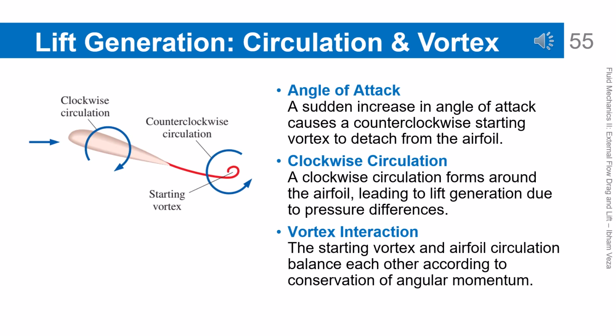Lift generation through circulation and starting vortex. When the angle of attack is suddenly increased, a starting vortex is formed and shed from the airfoil. At the same time, a circulation develops around the airfoil in the opposite direction.